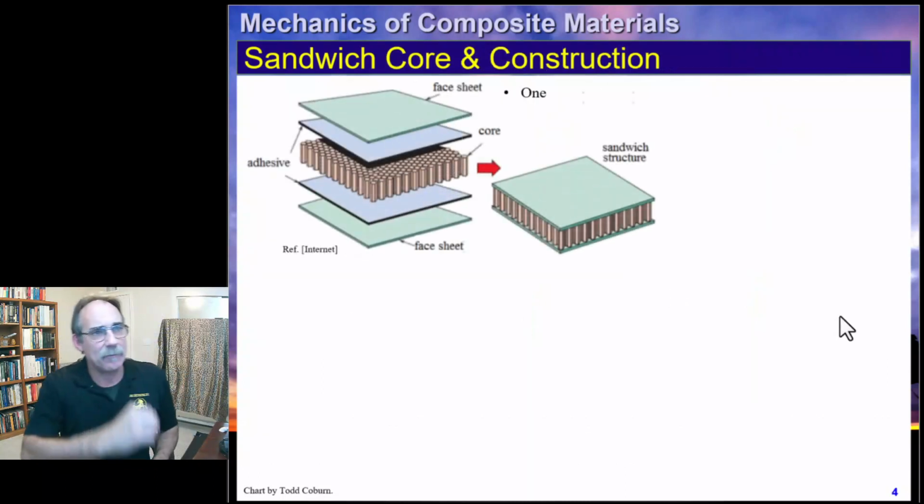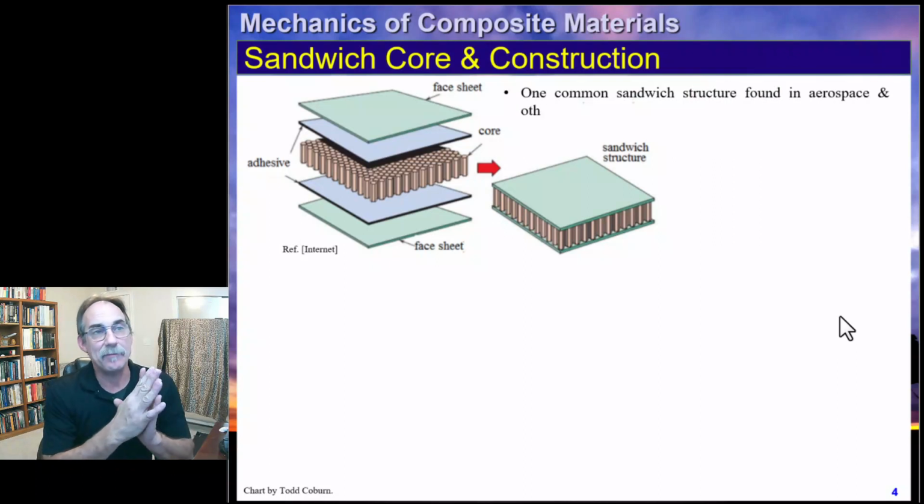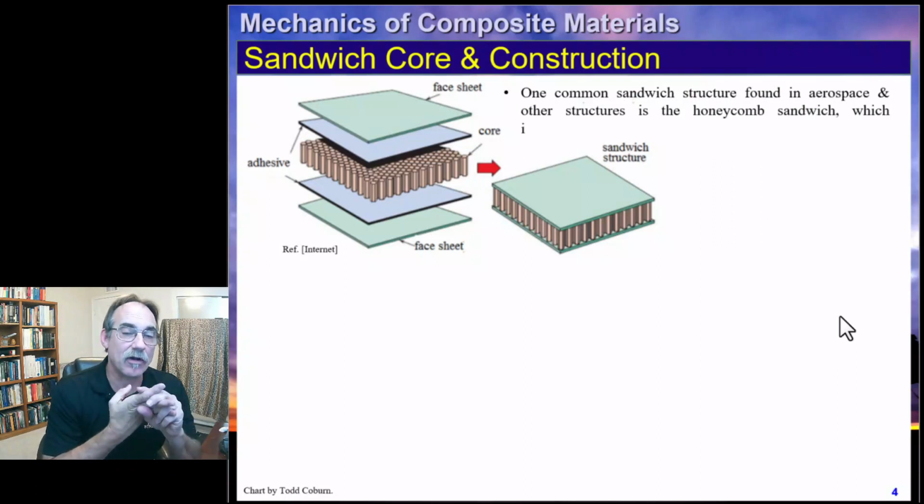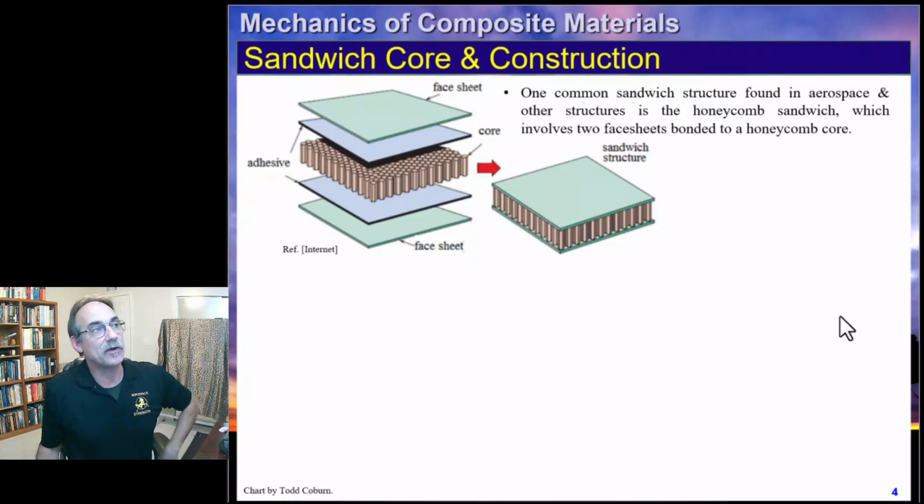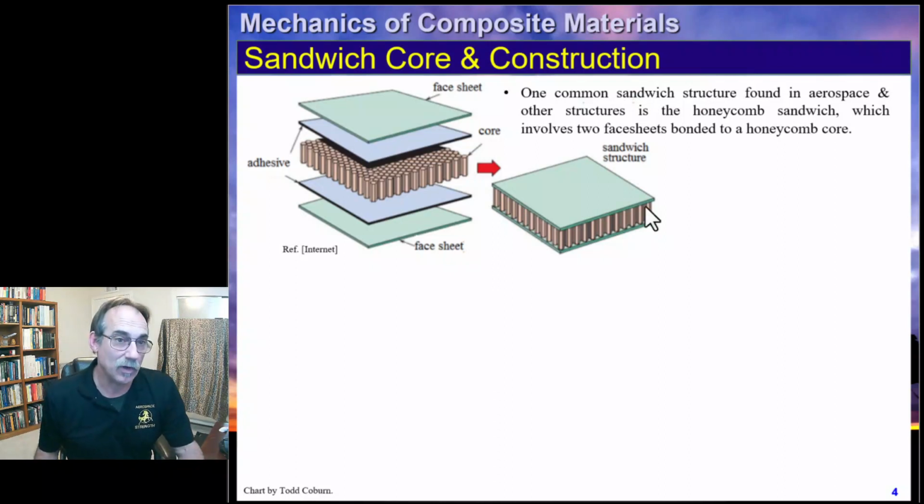Now, these pictures, I've got a couple sketches in my book. I pulled some of these, which are a little fancier, off the internet. This shows a typical sandwich construction. The face sheets are often aluminum, or they can be steel. They can be really any material, including wood. A lot of times composite, graphite epoxy, or fiberglasses are used. You name it, you can take different face sheets.